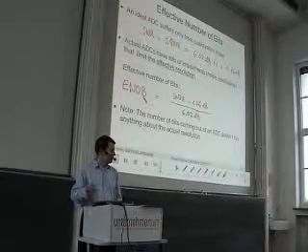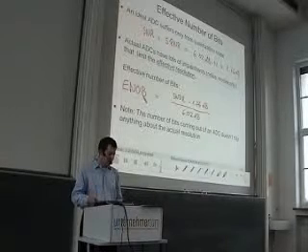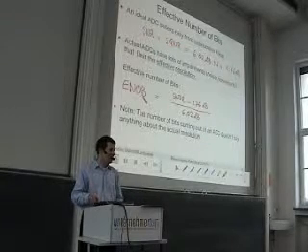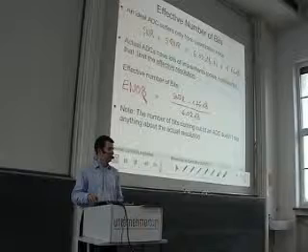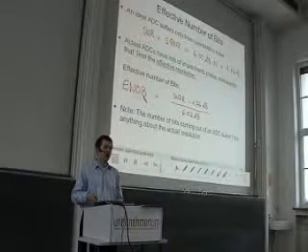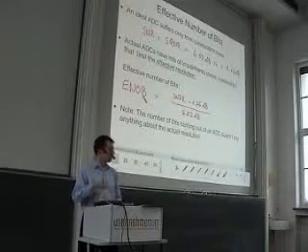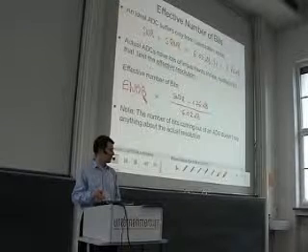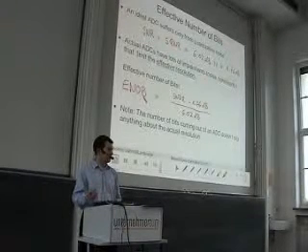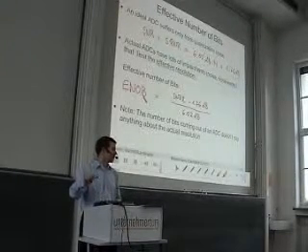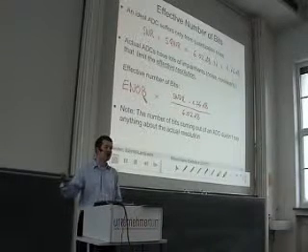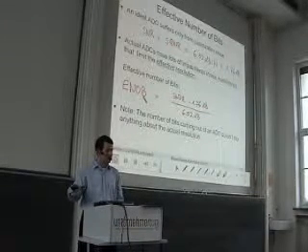You have to learn that the number of wires coming out of an ADC does in principle not say something about the resolution of this device. If there is lots of noise, then the LSBs carry only noise information.